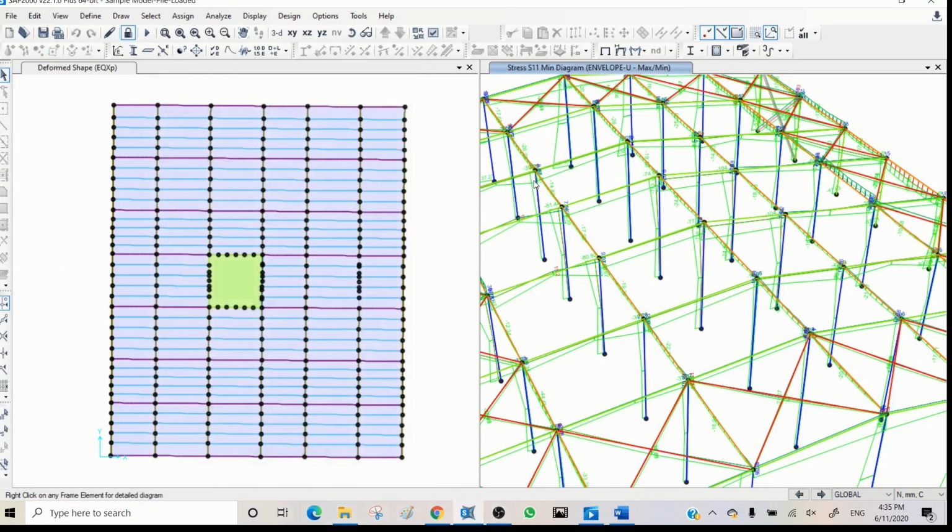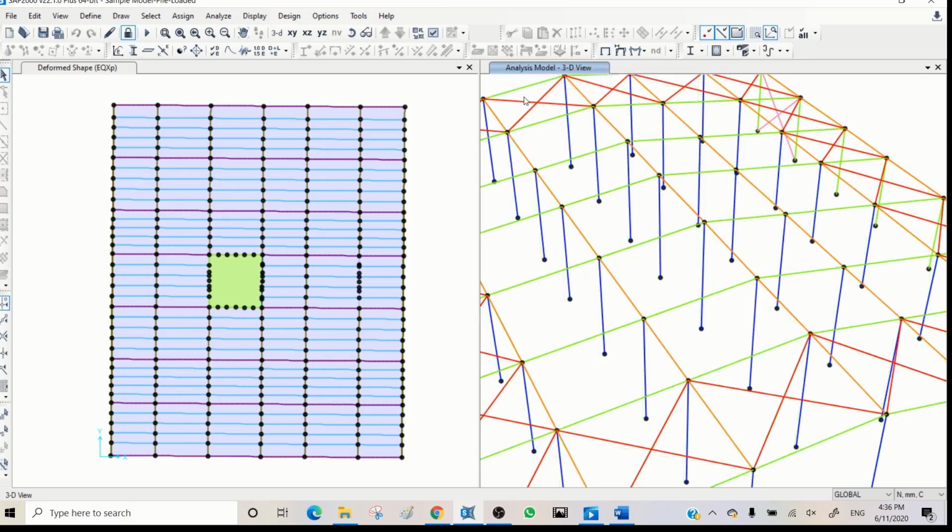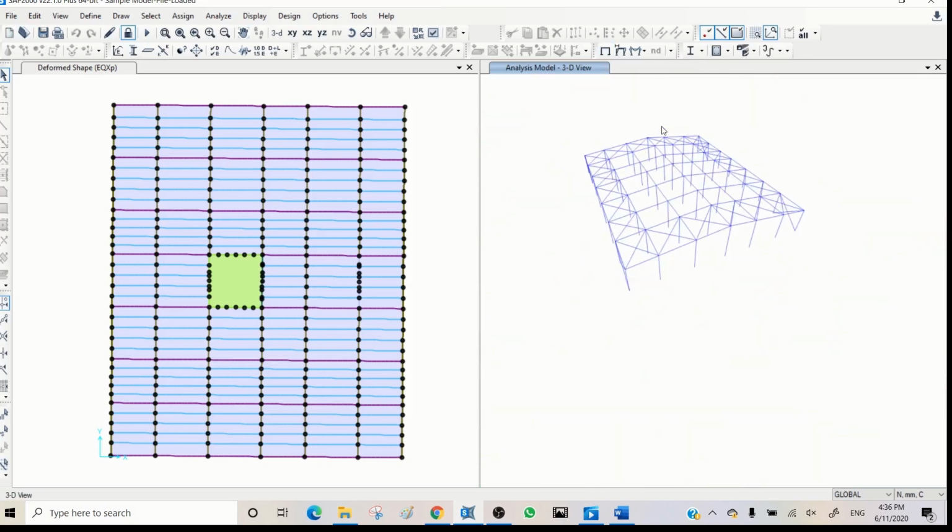Let's see why we had irregular compressive loads on the frame. There must be a reason. As I said, we need to review the result of analysis. We need to review internal forces to ensure the analysis is accurate enough to move on for design. Otherwise, many people just see, okay, SAP doesn't have any error, so we can simply go and start our design. But this could be very dangerous.